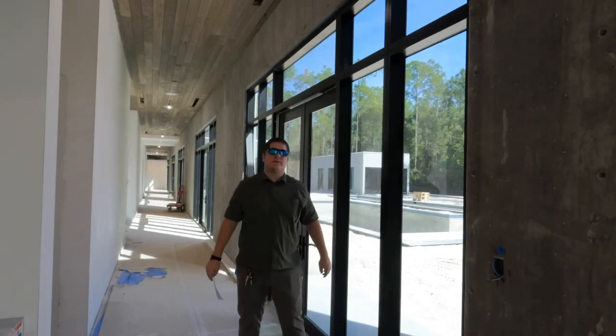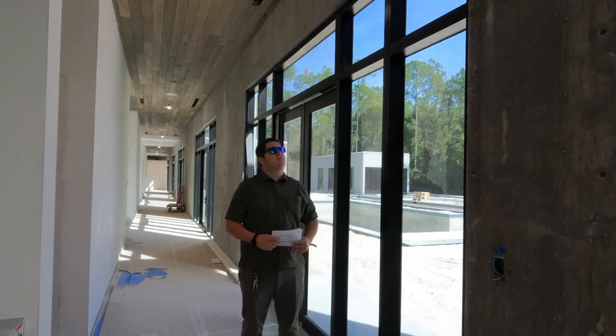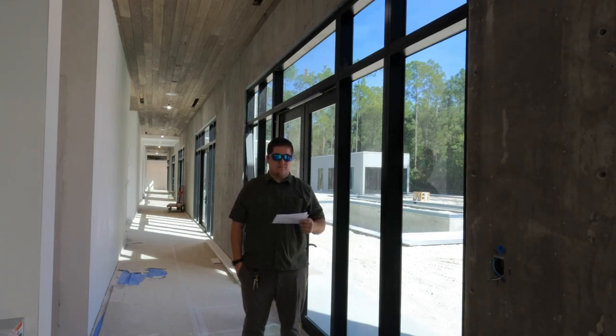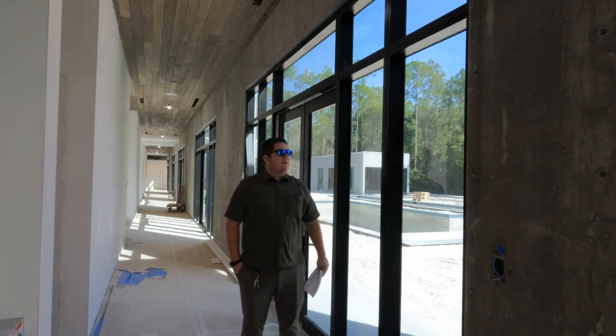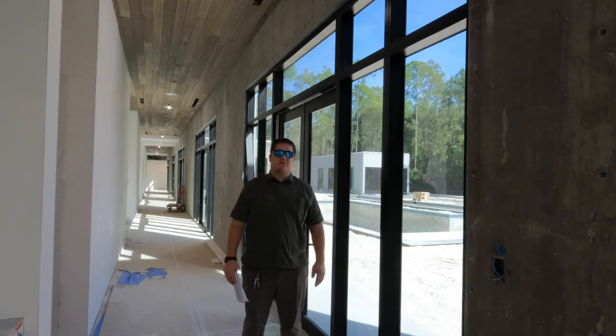So the first part of the building envelope that I'd like to talk about is windows. These are CGI storefront windows. They're low E glass. Low E glass, or low emissivity glass, was created to minimize the amount of infrared and ultraviolet light that comes through your glass without minimizing the amount of light that enters your home. That means that it'll let the light in, but it doesn't let the heat in. Therefore, you don't have to pay as much to cool your house down.